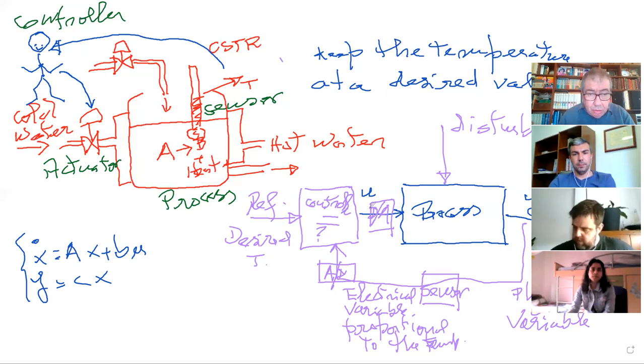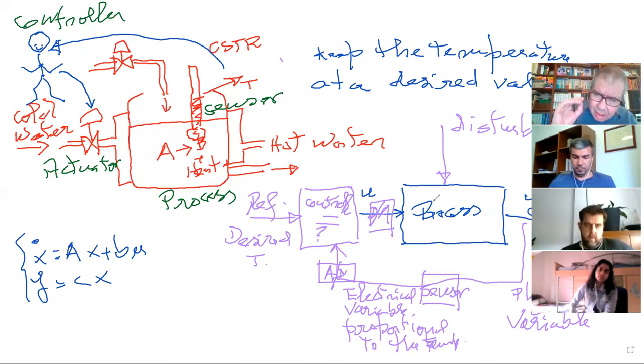The opposite is true. Say position number 11 is an output port, so you can write on it. You connect a DA, so you write a number, and this number is transformed into an electrical tension, and this electrical tension then excites a motor related to the valve. Usually valves don't have motors; it's compressed air, an electromechanical device. But okay, let's think about that. If you give it an electrical tension, they work. They do what you want.